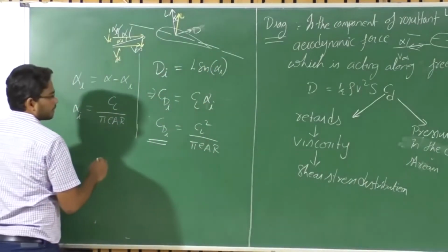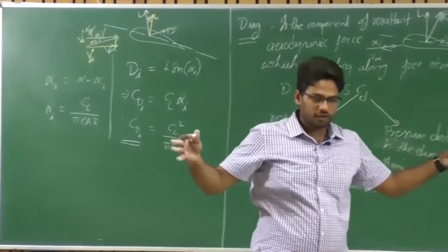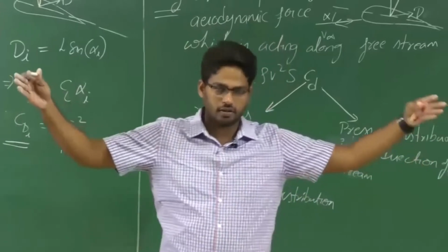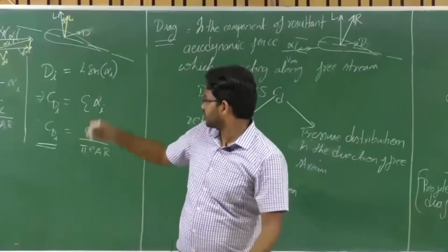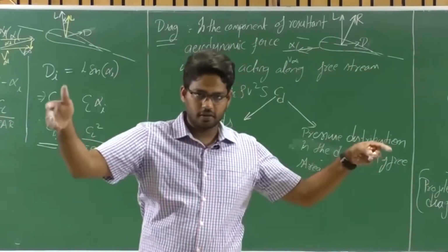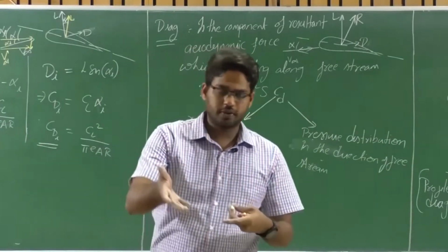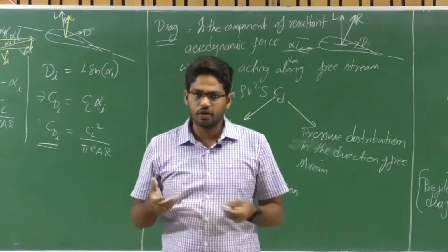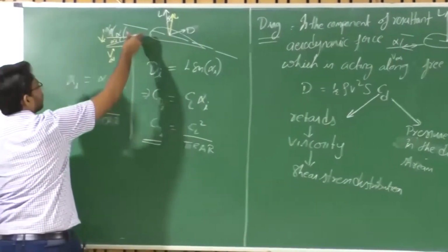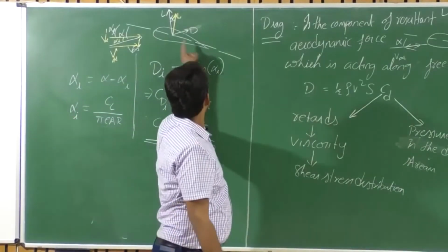Apart from this, if you consider a finite wing, it has tip vortices near the tip chords. Those tip vortices will try to drive the air along the spanwise direction, and then there is the wing, which creates an upwash ahead of, upstream of the wing, and downwash in the downstream of the wing. So all three together will induce a certain angle of attack, or will alter the local flow and produce this induced drag, right? So there is a contribution of lift to the drag.